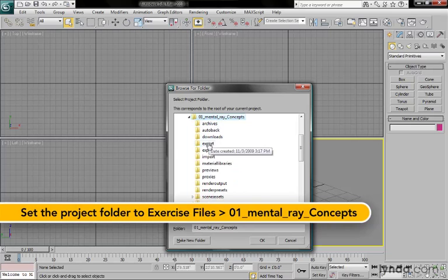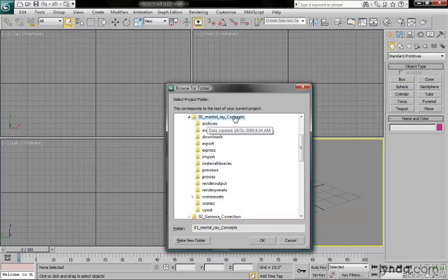You'll see a bunch of mysteriously named subfolders inside there. Those are all of 3ds Max's project folders for different data types. Again, the relevant ones in this case are Scenes, which is where your 3ds Max geometry scene files will be stored. Scene Assets, which is where images and photometric data files will be stored. And Render Output, which is where your finished renderings will be found.